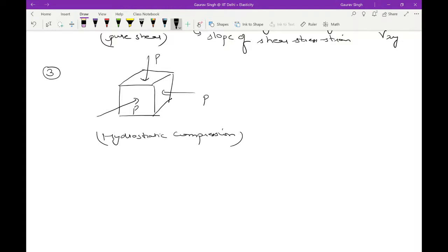It's just that it's easier to perform this, and civil engineers have a very nice way to do these tests. What they do is they put up a piece of rock sample and then surround it by oil from all sides, and then they apply the loading so that the pressure generated in the oil is then applied to these rock pieces. So they call it a triaxial loading, meaning this load is applied on all the three axes. So you have to choose a suitable geometry of the specimen, but the ideas remain the same.